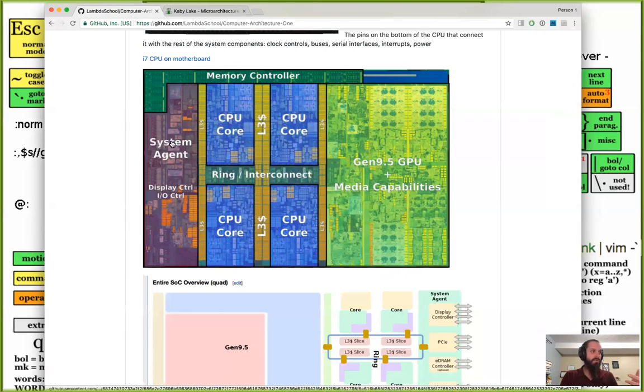the USB mouse without them interfering with each other at all. It's a whole other CPU located inside of the system agent. And then when the mouse is finished with its command, or when the user presses a key on the keyboard, it activates an interrupt in the system agent, which tells whichever CPU is interested in that particular piece of hardware to work. Okay, here's the memory controller. This whole machine is responsible for addressing the memory that's located on that DMA bus, and then reading and writing memory from it, and then notifying which CPU asked for it when it's ready.